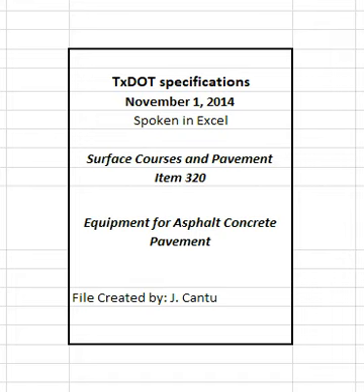2.1.1.2 Reclaimed asphalt pavement, RAP, and recycled asphalt shingles, RAS, feed systems. Provide a minimum of 1 bin for each stockpile of RAP and RAS to weigh and feed the recycled material into the hot mix plant. 2.1.1.3 Mineral filler feed system. Provide a closed system for mineral filler that maintains a constant supply with minimal loss of material through the exhaust system. Interlock the measuring device into the automatic plant controls to automatically adjust the supply of mineral filler to plant production and provide a consistent percentage to the mixture.